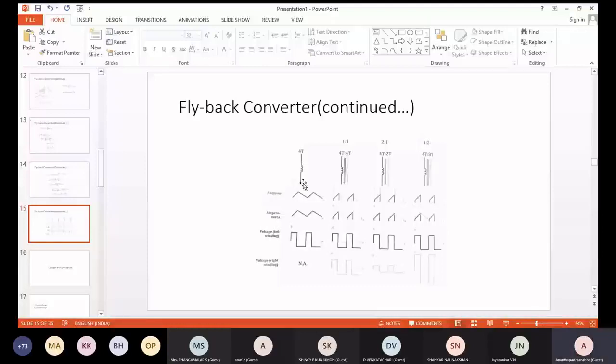But that other path has taken the energy from the same stored energy. So the energy is not different, only the path is different. Whereas here, the energy is the same and the path is also the same, that's why you can see the continuity. You cannot see the continuity in the coupled inductor; an abrupt fall is there, but exactly at that time the other winding picks up. That is what you mean by a coupled inductor.